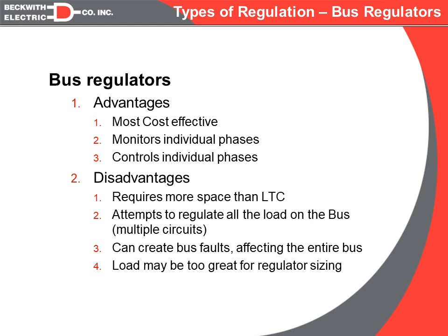A possible disadvantage for bus regulators is the sizing. Right now, the largest single phase bus regulators that can be purchased are 833 kVA, and therefore, if your transformer is too large, you will not be able to use bus regulation.